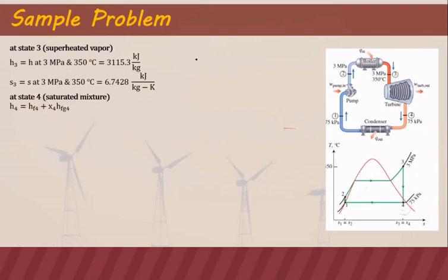But we do not have the values yet. That's why we will use the steam table. We will have to use the steam table in solving for the quality X4. Now we know that this is a mixture, so basically our entropy can also be calculated at 0.4. The entropy can also be calculated using the same formula, but now in terms of entropy S.